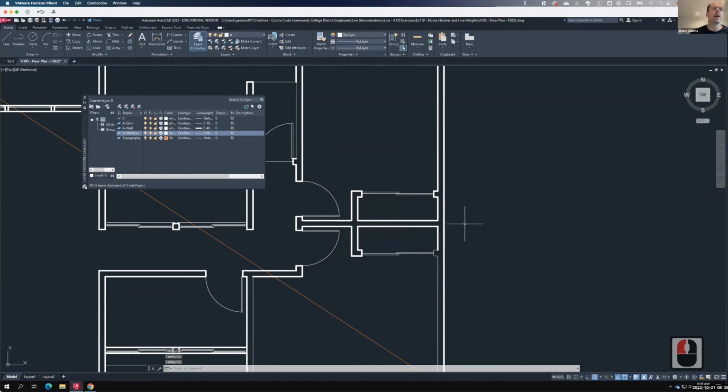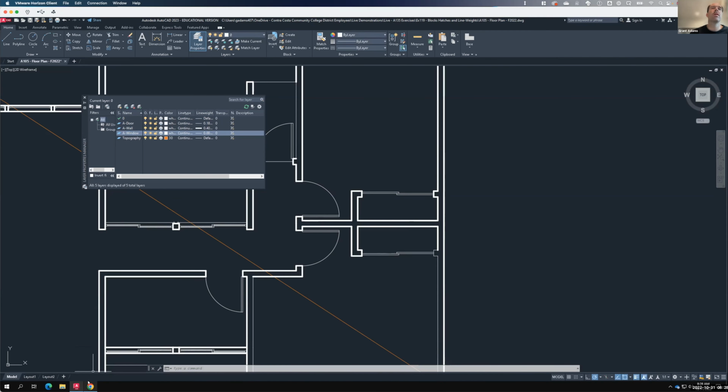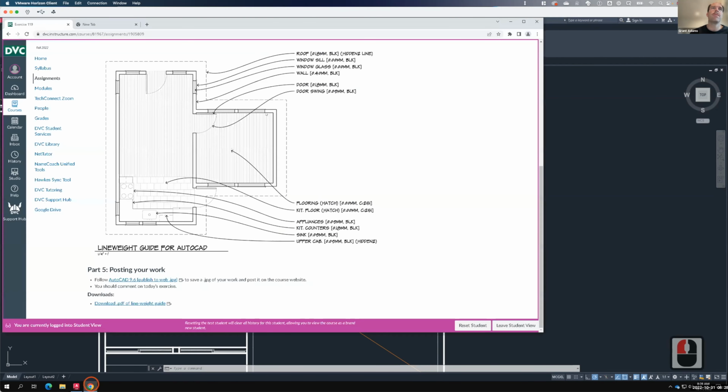So the first part of what we're working on today is essentially organizing your file. So you've already drawn the floor plan, hopefully. If you haven't, guess what? You get a little extra time today to work on your floor plan a little bit more. And then after that, we're going to make sure we're organizing our file such that we're setting up our layers, A-wall, A-door, A-window, etc. I tend to also do an A-fixtures and an A-furniture, and that's what we're going to come to next.